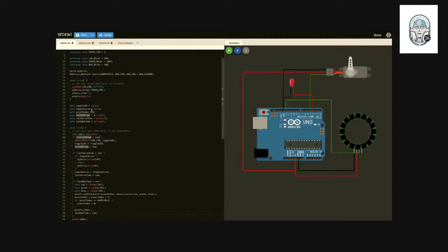All right, I didn't actually put in a time. So the last LED time plus LED delay. Sorry. So you want to have it greater than 500 milliseconds, 1 second, and 100 milliseconds. So plus here, and I would say plus servo delay and plus Neo delay.